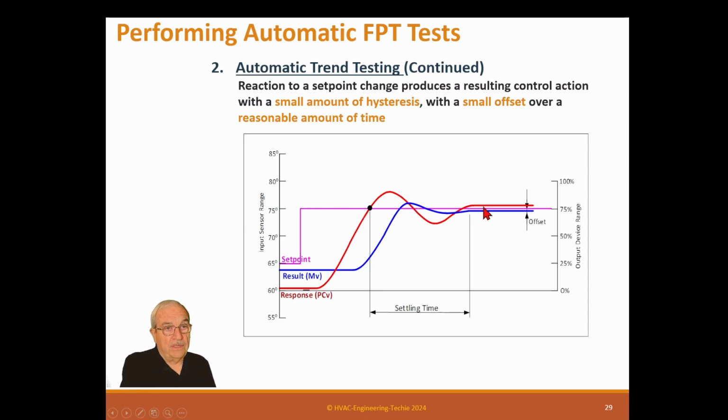So whatever color that is, that's the set point. And this down here is the valve. This is what the valve is actually doing. So the valve is kind of cruising along. It's closed because the temperature was satisfied at 65 degrees. So this is closed. And then the difference between this and this is the reaction time of the valve.